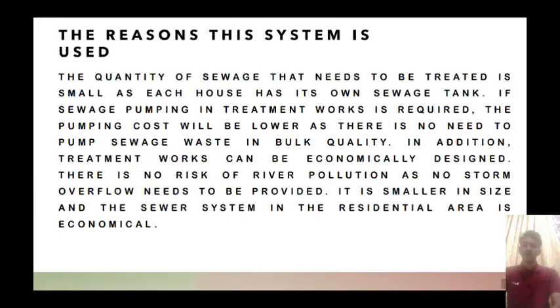The next is the reason this system is used. The quantity of sewage that needs to be treated is small, as each house has its own sewage tank. If sewage pumping and treatment works are required, the pumping cost will be lower, as there is no need to pump sewage waste in bulk quantity.